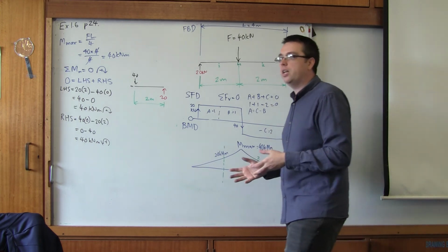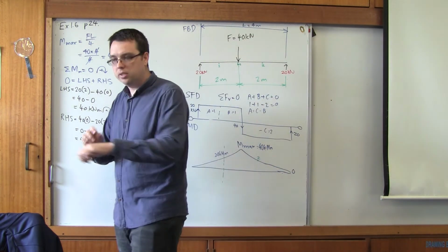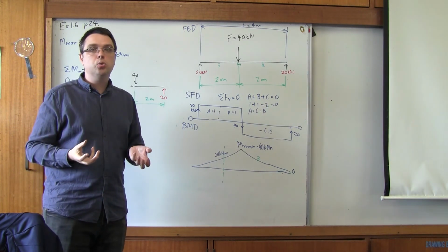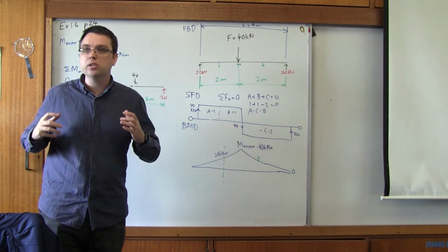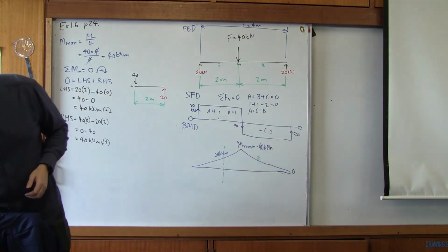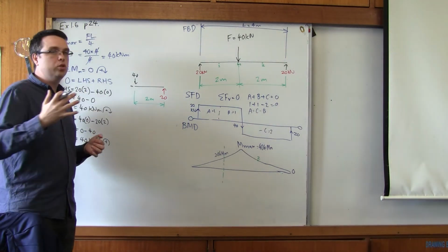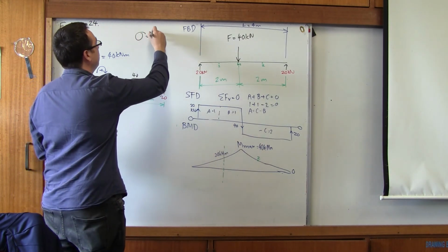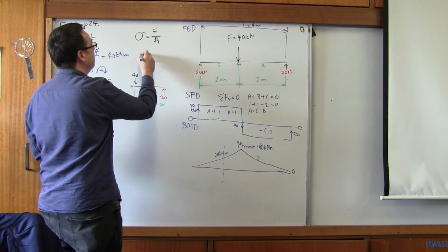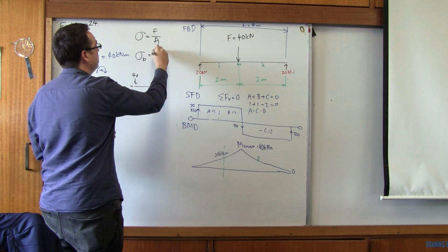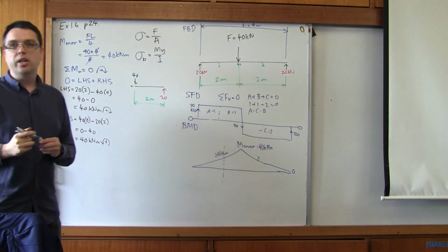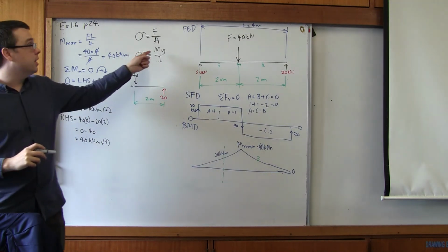Now later we'll find out how we can calculate bending stress. I'm going to say this expecting the bell to go any second: bending stress is different to the regular stress formula. I have said that in this subject the second most important thing you need to know is that stress equals force over area, unless it's bending stress, in which case it's My over I.